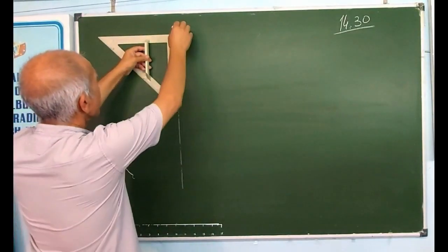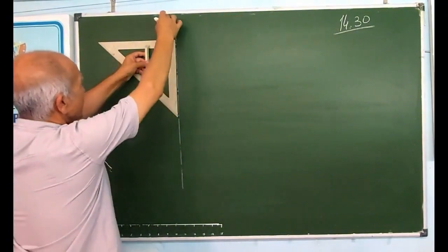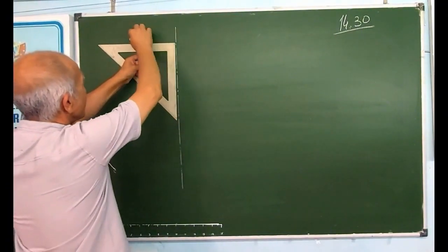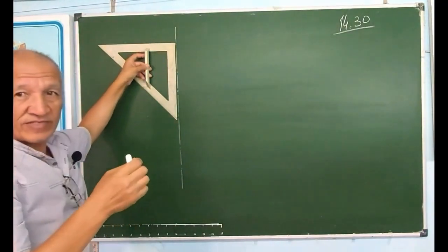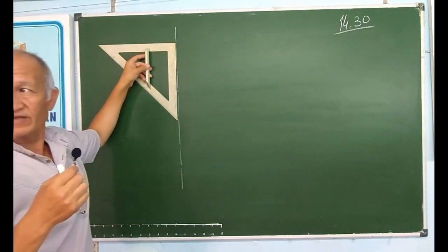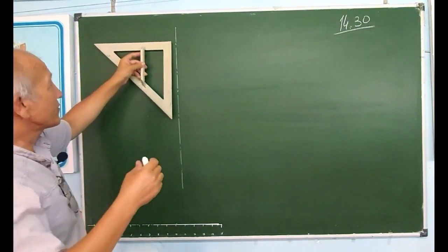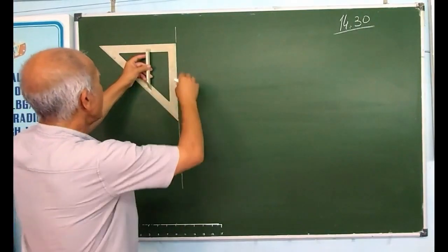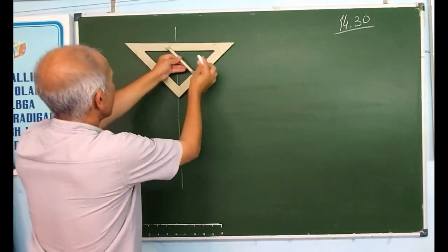After placing it for the height from the top, you already have a 5 millimeter mark. In your drawing, let's say you leave about 15 or 20 millimeters, maybe even more, I'm just saying. It doesn't have to be exactly 15 or 20 millimeters. The detail also depends on the size of the sheet. There are calculations involved. Taking those calculations into account, you do it perpendicularly. You draw a thin line here, make it perfectly perpendicular.